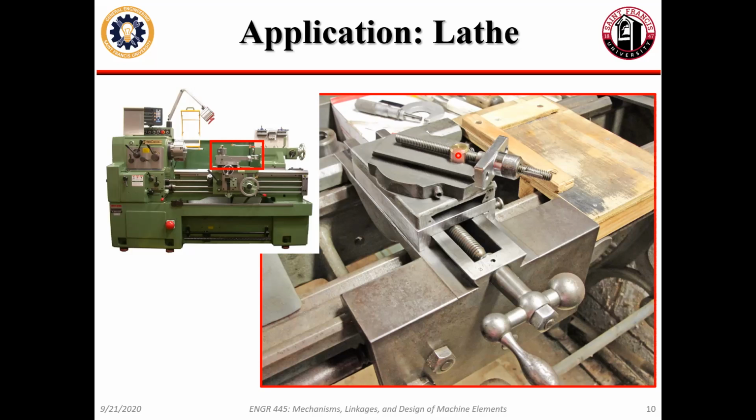Like you don't need to make some intense telescoping rod in order to get my compound rest to move. I just need to put a nut onto a screw that runs the length of however far I want the thing to run, right? So it's a really straightforward way to do that. And because a thread is a helix, essentially it's just a wedge, so it's a relatively efficient mechanism. And by efficient, I mean a means of applying a longitudinal force from a rotary motion or from a sideways motion on the small scale. So that's screws for you.